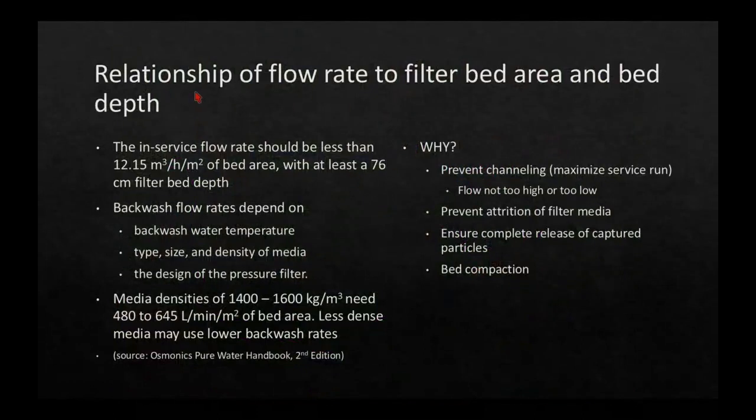So here's some stuff. Just want to put this in your back pocket. You don't get tested on this, but this is from the Osmonics Pure Water Handbook. You can find this online. It's free for download as a PDF. It's more designed toward potable water production than it is for powerhouse production, but the same principles apply. And so anyway, they say that there should be a particular in-service flow rate, and it depends upon the surface area of the bed and the depth of the bed.